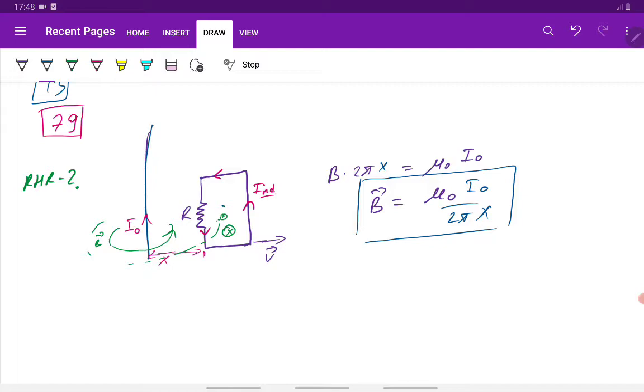So in that case, let's write the formula of the magnetic flux: the integral of B over area, B dA. B is given, right? What is dA here? This distance is changing as a function of time. So dA is the area of this circuit.